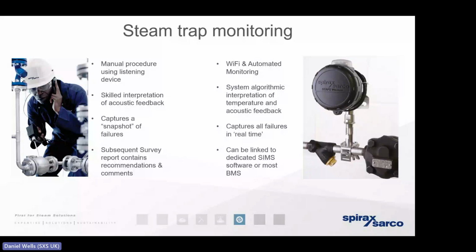An audit or report can quantify that inefficiency in financial terms so the client can understand the financial implication of not maintaining or replacing those traps, and it can make the appropriate recommendations for bringing the wider steam trap population up to optimal performance. Certain critical applications could have automated trap monitoring. But when a steam trap's failed in the closed position, the implications really depend upon where that trap's located.